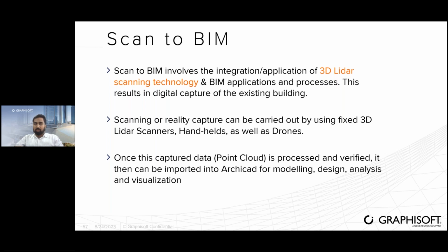Once you post process that, you can simply import that information inside Archicad, and then you can use that as a reference to create your model, to perform some design analysis or visualization as well. This workflow can be applied to cases where you don't have the BIM model for the buildings or even the drawings for the buildings that you have constructed, but you want to create a BIM model. You can use this workflow.